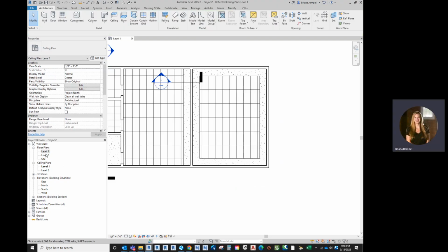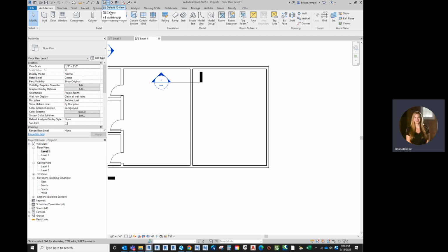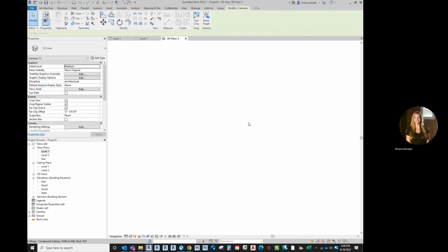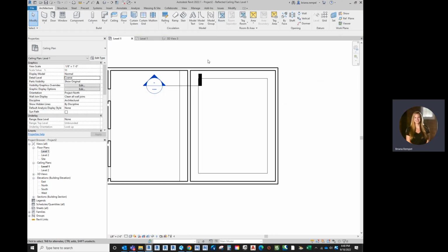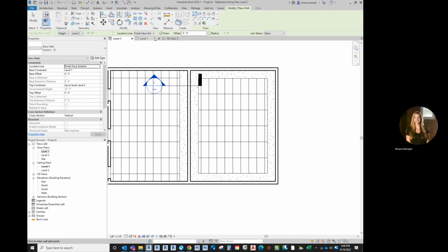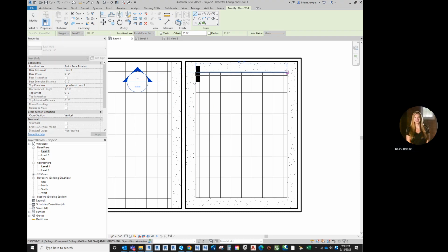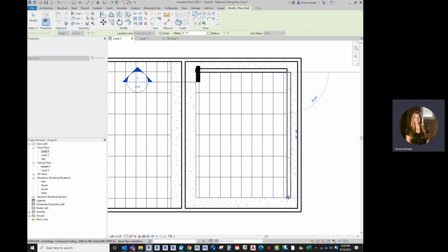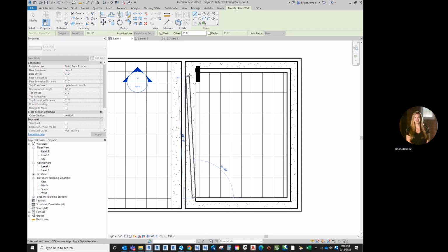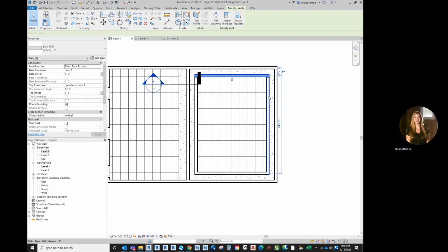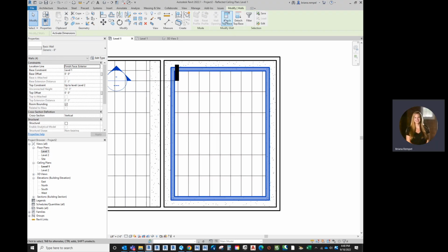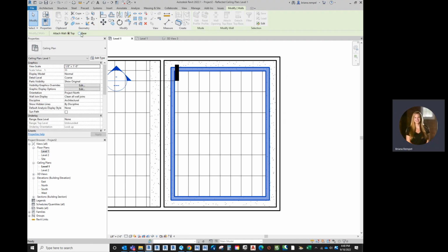All right, so this will be the similar thing where I will have a gap there. And I'll want to make sure that those are attached. So I would come back in and use my wall command, finish face exterior, and then make sure that it's on the side of the soffit, connecting the two. And then for this, even do it from the RCP plan. If I say attach top base, I want to attach the base. And no, it won't let me do it.